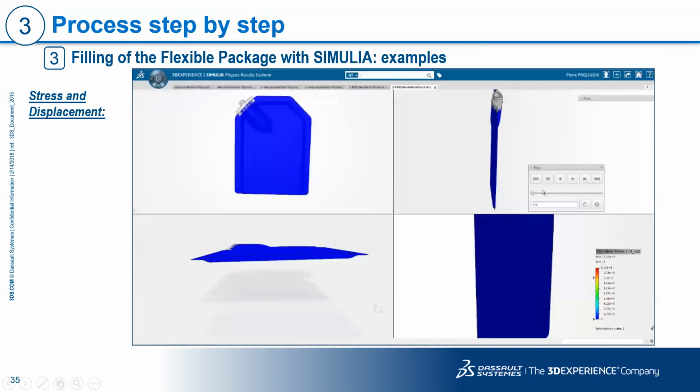and we run the simulation in the explicit solver, which is a part of the Abaqus solver. The idea behind explicit is that it is able to handle higher deformation much more easily, without getting into too much technical detail. It doesn't try to solve the whole system of equations simultaneously.